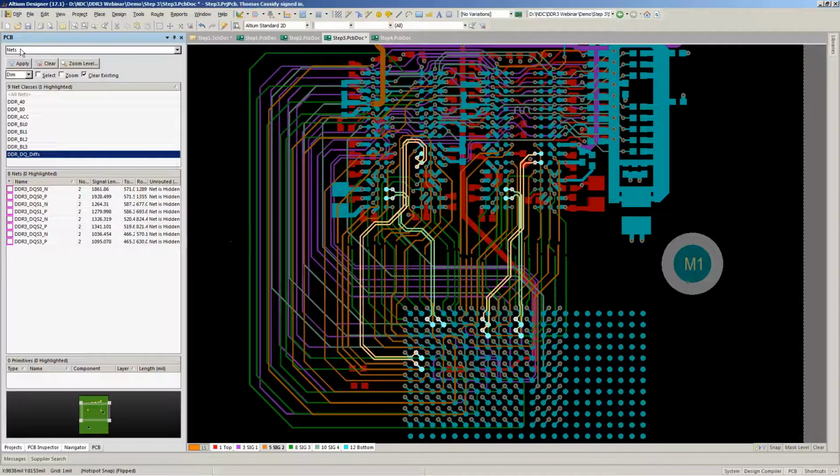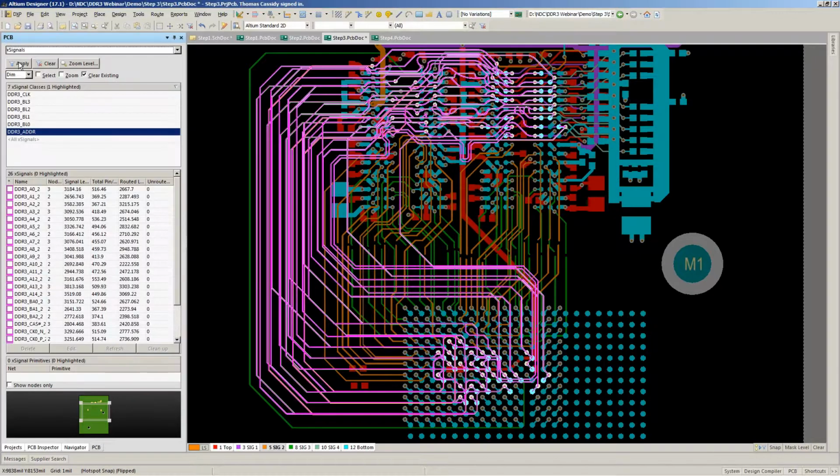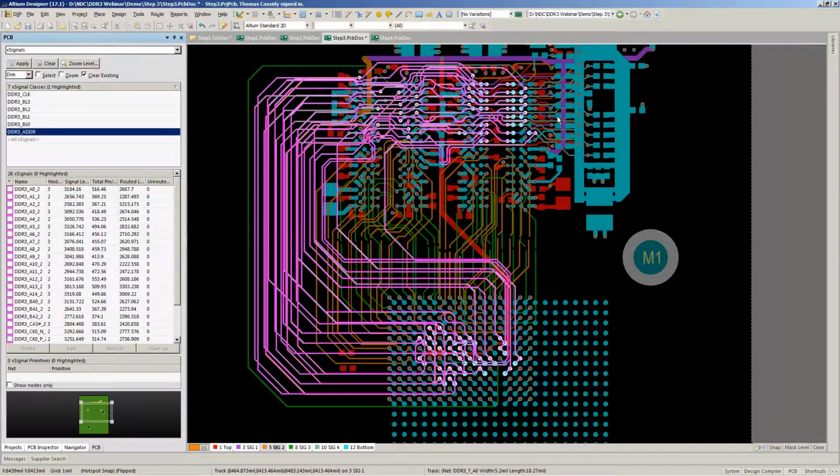Let's see. At this stage is also when you might want to define what Altium calls xSignals. And xSignals are basically a way of combining nets, because on a net list, especially if you have termination signals or you have stubs going from one chip up to the pin coming back down, it's often very hard to calculate the actual electrical length based on just the net names.